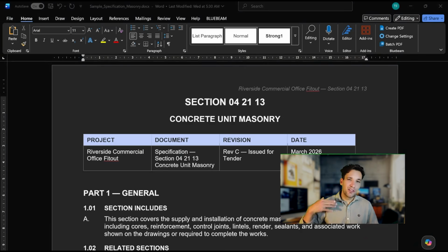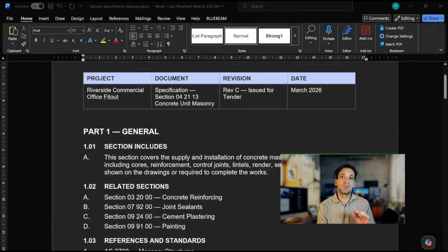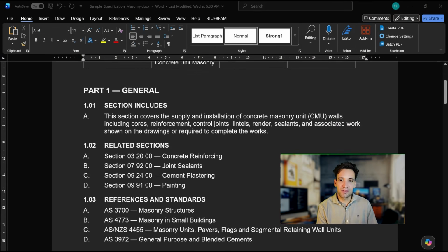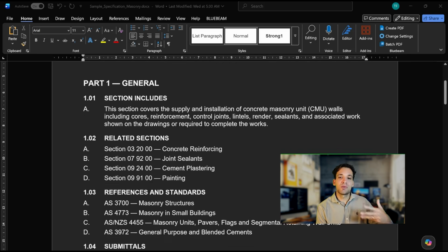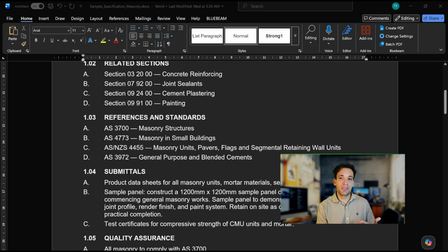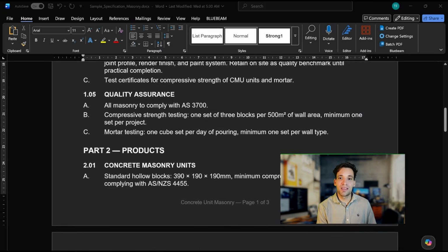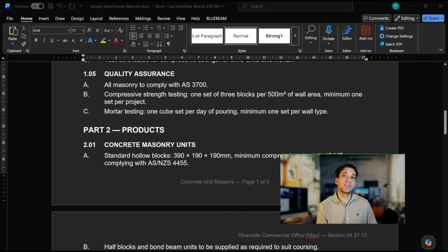Okay, so we understand the drawings and the physical representation of the construction. I just very briefly want to talk about specifications. So basically, a drawing will show you what everything is and where it goes, but the specifications really add supplementary information to this. Again, a lot of this could be within the general notes, or it could be within a separate document referred to as a spec.